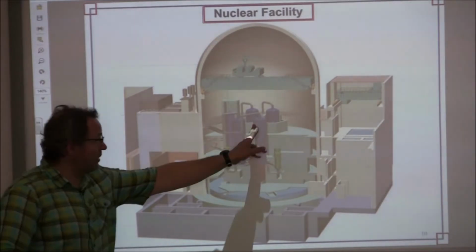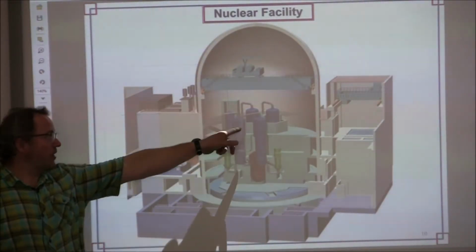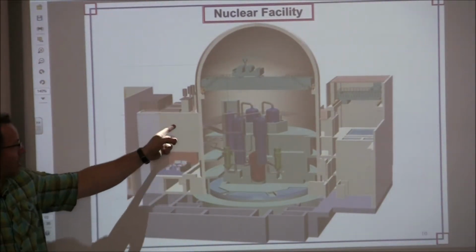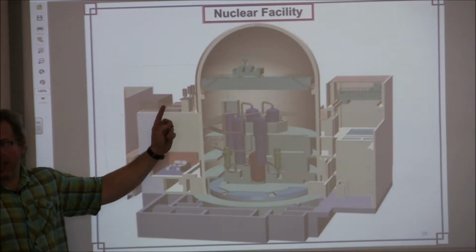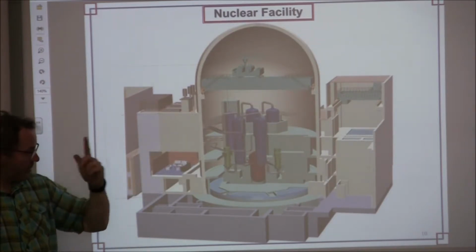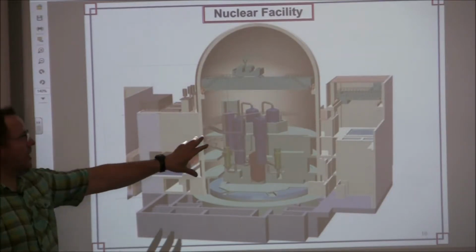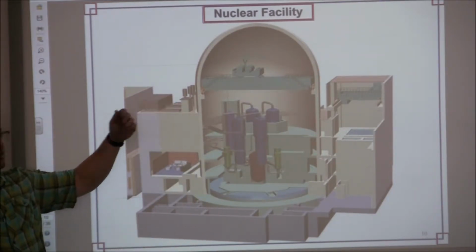It doesn't flash to steam, but it's run through these heat exchangers, which are called steam generators, and the output of those goes into your turbine areas and goes ahead and does that. All right? So that pressurized water reactor would basically be, its whole purpose in life is to maintain pressure. So they might run at 560, 570 degrees, but the pressure inside the reactor is 2,000 plus pounds. Very high pressures to make sure it doesn't flash to steam. Over here, you might be 1,000 psi so that you can flash the steam.